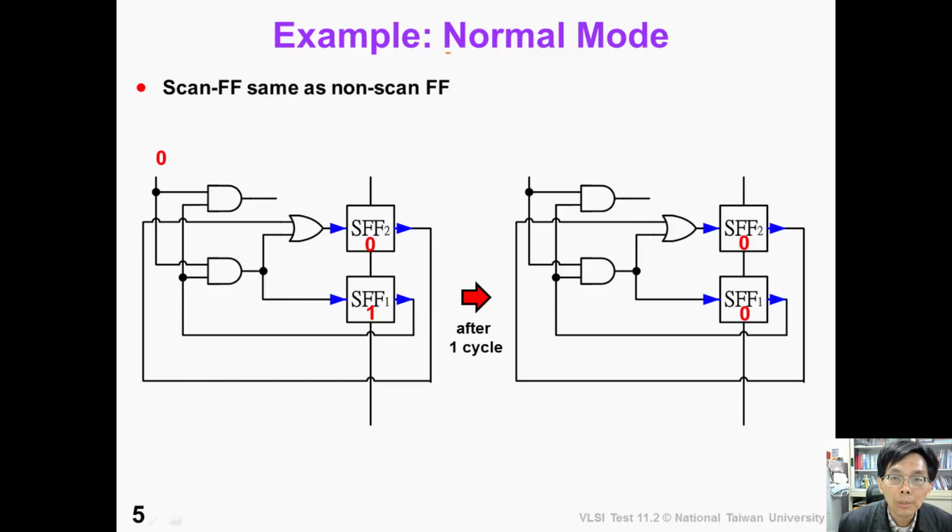Now, in normal operation mode, the scan flip-flop is actually the same as a non-scan flip-flop. In this mode, the scan flip-flop will capture data from the data input.